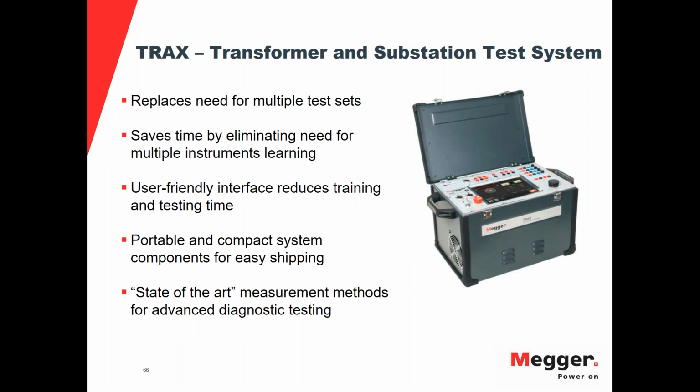Talk about Trax. Trax is kind of our, what we like to call it, all-in-one box. It does a lot of different testing for one unit. It's substation testing, everything from CTs. You can do power factor. You can do excitation current. You can do a lot of different things with the circuit breaker testing. TTR, winding resistance, even a DLRO.